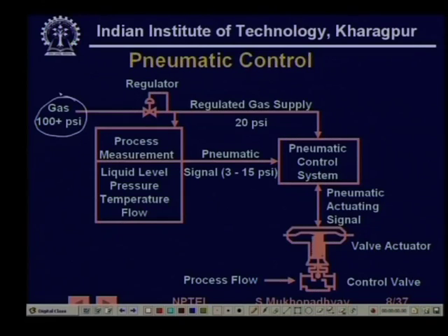This source is generally coming from the compressor, and then you have a regulator, and this is actually a pressure regulator. After that you actually get the gas at the pressure that your equipment will require. Similarly, you can also have feedbacks, you can have pneumatic signal feedbacks using things like I2P converters,